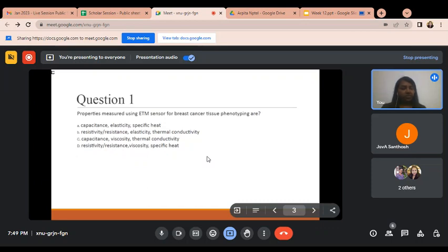So what is present in the piezoelectric pressure sensor? Two types of fabrication are needed: one is surface micro machining, and the second is bulk micro machining. When we go for bulk micro machining, we etch the bulk portion of the substrate. And surface micro machining is when we do the microfabrication process on the surface.